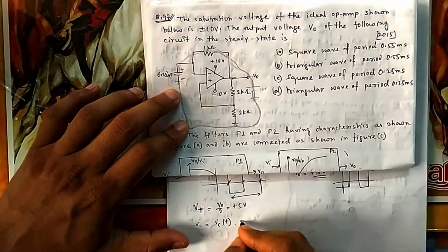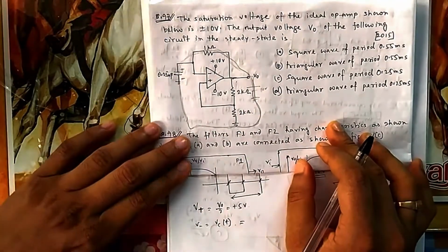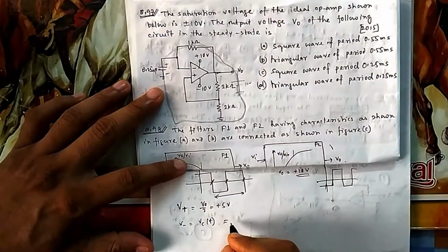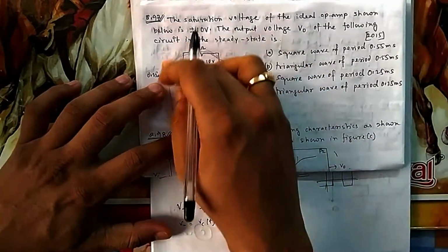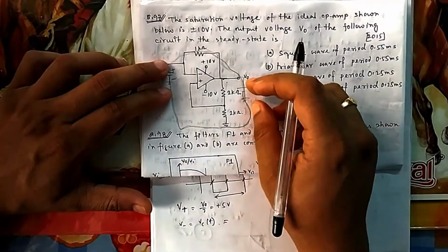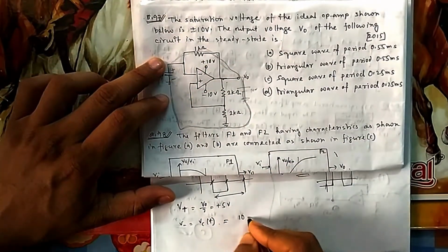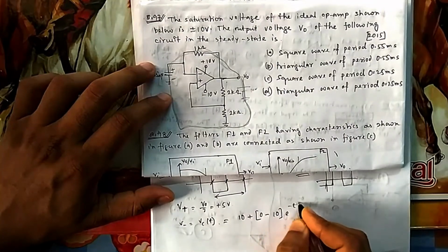Okay. Now if it is in charging mode, then what will be its expression? So what is that guru mantra, that good mantra that we have studied? It is Vc infinity. What is the infinite voltage? If you keep it on for infinite time, finally its potential will be equal to this potential. No current will flow. It will get fully charged. So final voltage is 10. What is initial voltage? 0. Final voltage is 10, e to the power minus t by RC.